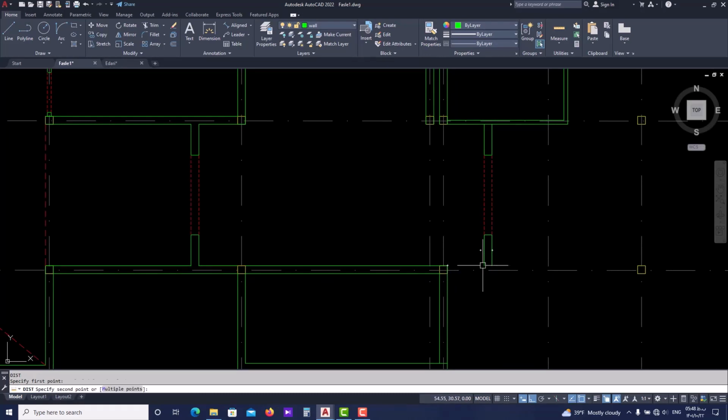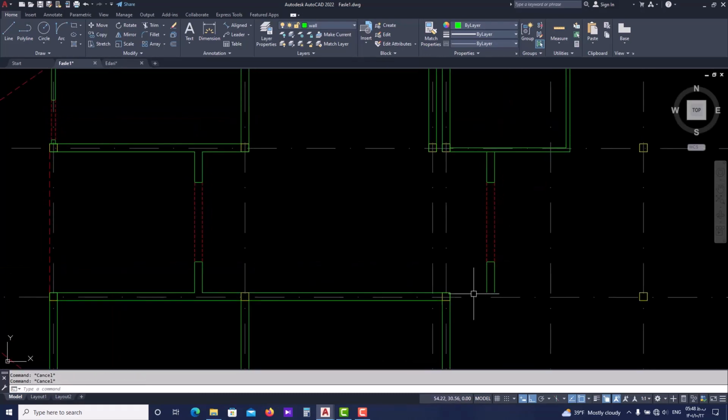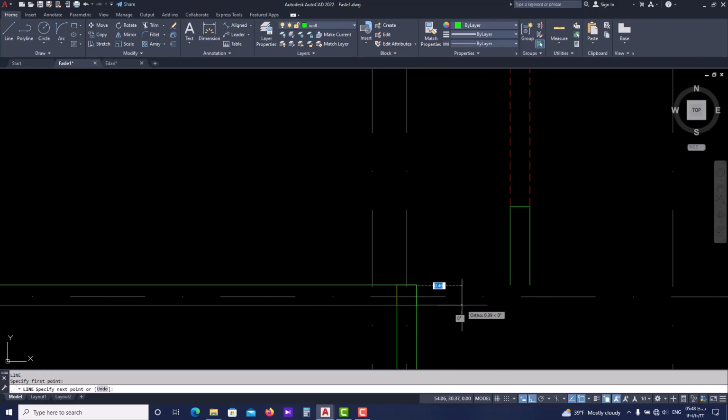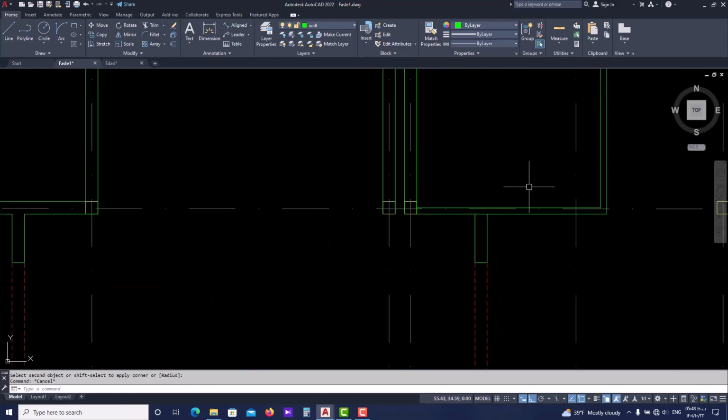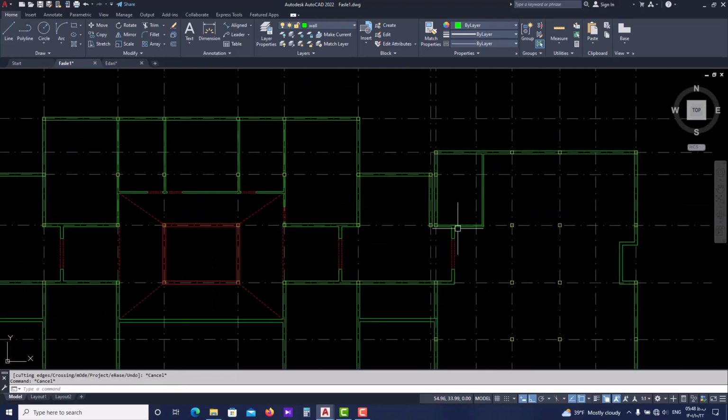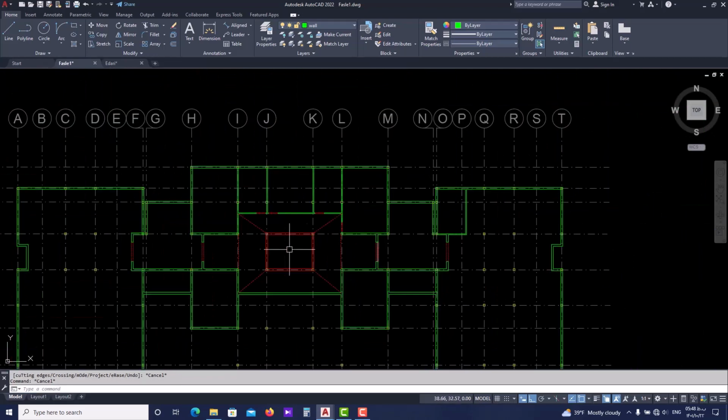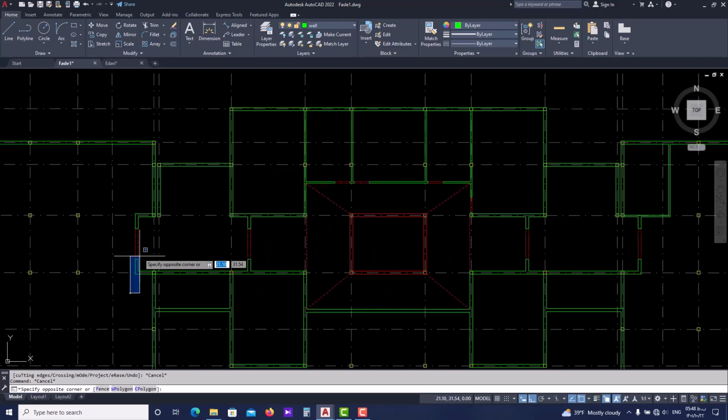95. Okay. Now for this part, L enter, draw the lines. Then F enter, use fillet to connect them. And we have 220 cm offsets as well. Just like this, okay. And trim. So you have to pay attention to these areas. Sometimes 2 areas might appear completely similar, but they aren't.